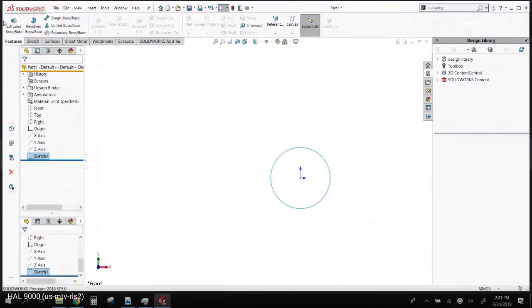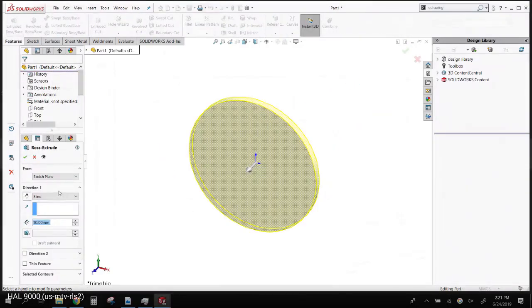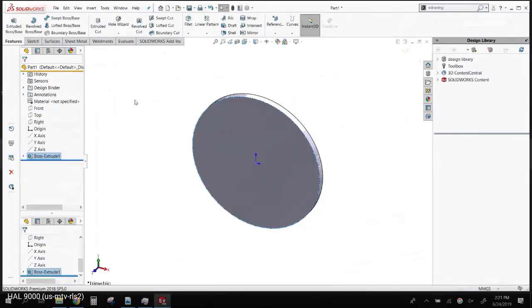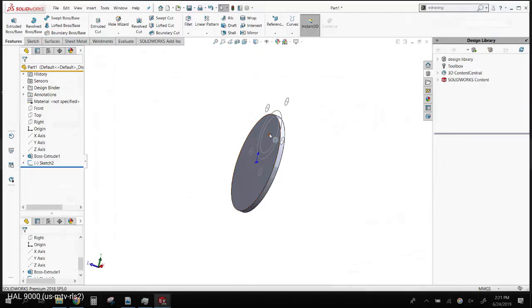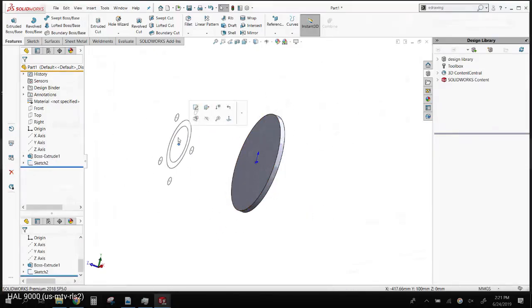And for this part, I'm just going to put a little base on here. Then I'll pick this face, Control V, there's my block. So the block moves as a unit, where usually with sketch geometry, if you click and drag on sketch geometry, if it's underdefined, it just gets dragged all over the place because it doesn't know where it's supposed to be. But when you save sketch geometry as a block, it moves as a single unit.